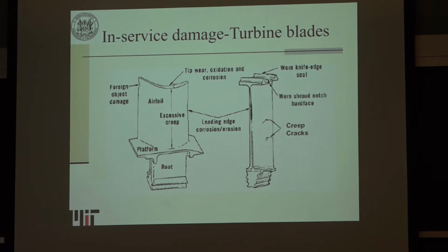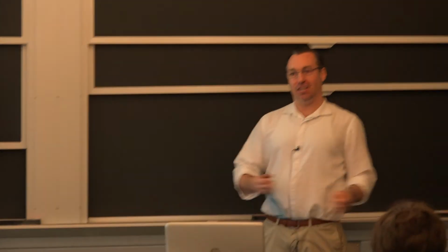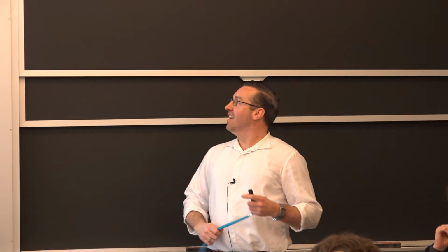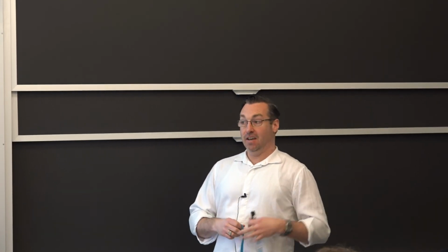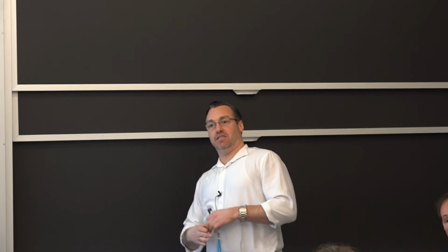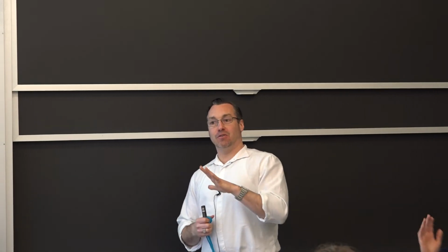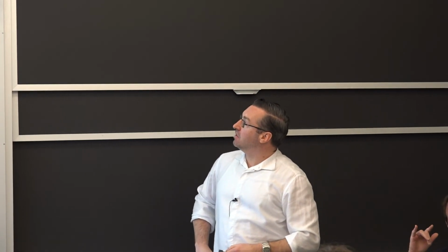Before they certify an engine, they'll do various tests. So they'll do an ice test where they put ice chunks through. I have a video where they throw dead chickens through the engine, and they do a chicken ingestion test. And if you guys have seen Miracle on the Hudson and Sully, it actually happens. You have bird strikes when you operate in rough weather. These things are going through the engine while you're going through the air. So you have to design against it.